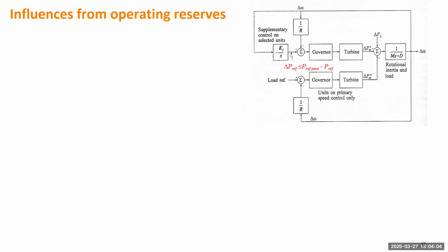Okay, next we need to discuss under what situations the AGC is available. It can be a very silly question. If you send the control signal to the setting point of the generator through the integral controller, eventually it will keep feeding that signal until the frequency really goes back to the original frequency, right? But that is based on an ideal assumption, so there's no limitation about the controller or the capacity of control. But here we have to think about the reality.